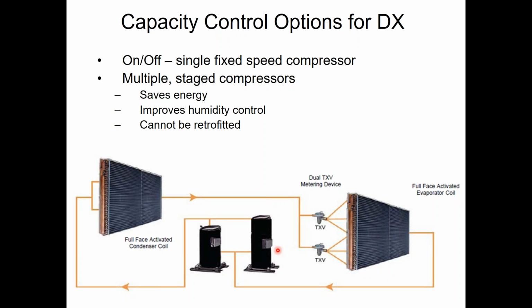The problem with that on a VAV system is I don't control space temperature like I do at your house or like I do on other constant volume systems. With VAV, I don't control space temperature. I control discharge air temperature to get my 55 degrees. Well, with one compressor turning on and off and my sensor being so close to the results of that compressor, basically my sensor is right at the discharge of the evaporator, if I turn that compressor on, I immediately am going to have like 48 degree air.